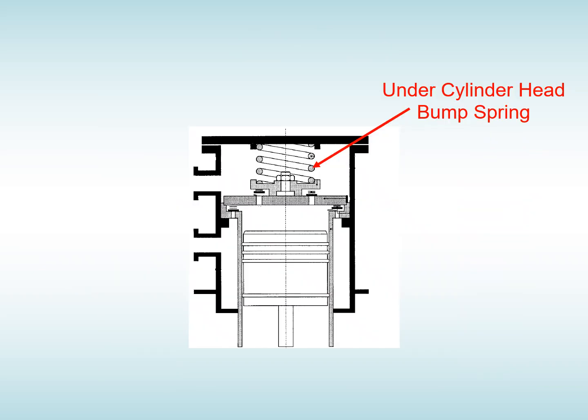And as you can see by this cutaway, under the cylinder head, there's a big old spring pressing down on the discharge cage. That's why you release the spring pressure gradually by using the long studs. Because I've seen in the past, people take off all the studs, give it a tap with the hammer, and that spring is very powerful.